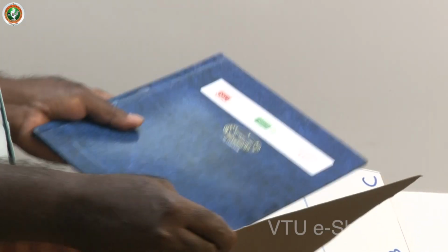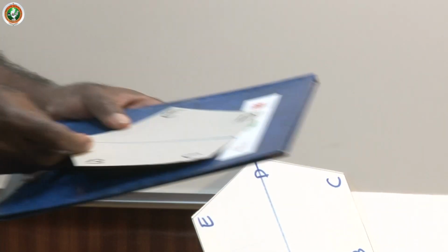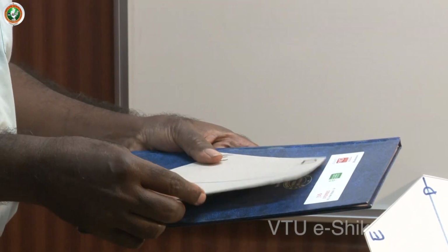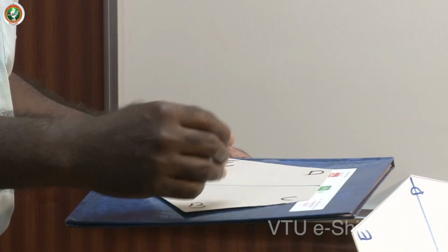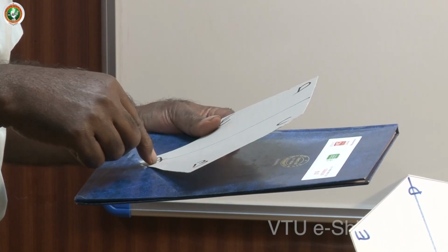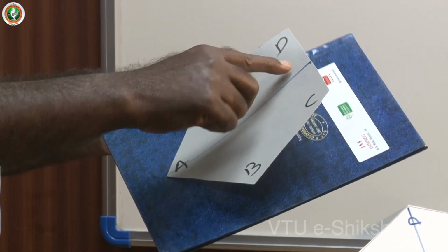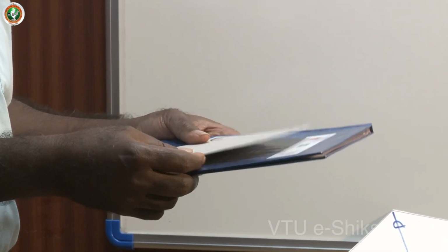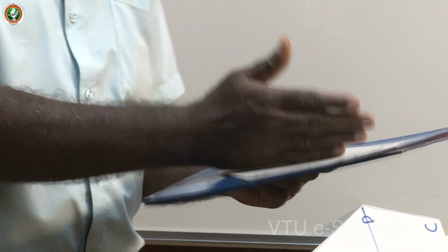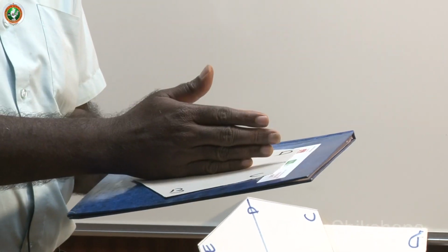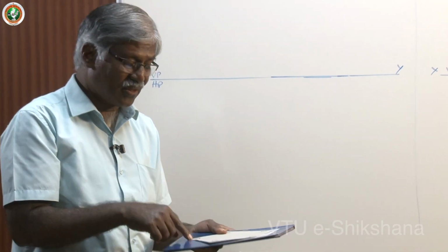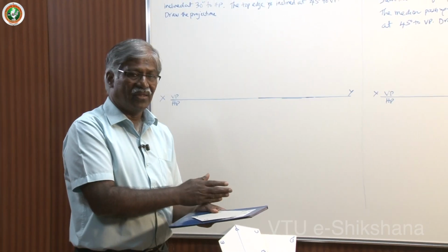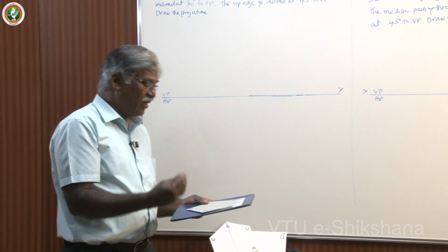So similarly, for a pentagon also the same thing. See, here corner on ground, I will keep it like this. So the opposite side must be perpendicular to VP initially. Automatically, this perpendicular bisector will be mutually perpendicular to these two. Definitely, this is parallel. So for all odd number of sides, either the median or perpendicular bisector must be parallel. For even number of sides, the diagonals passing through the corner must be parallel. So this is how we can continue with the problem.